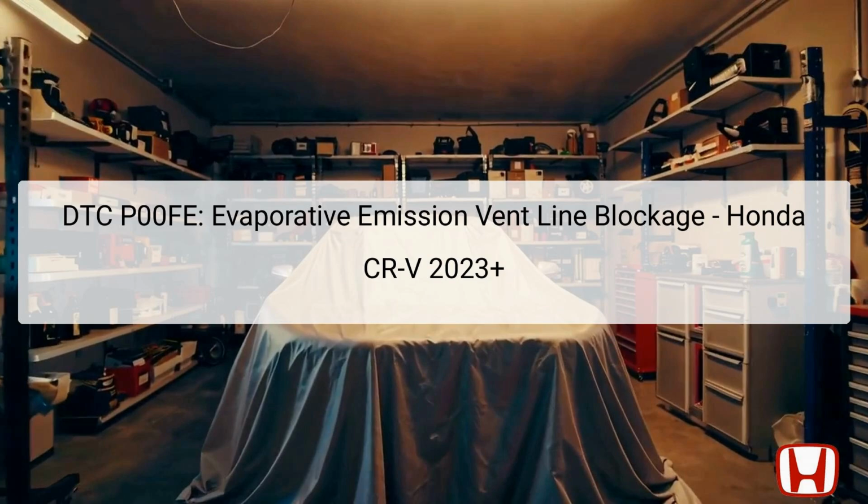The components involved include the EVAP canister, the EVAP purge valve, the fuel tank system, and the EVAP leak check module. These components play crucial roles in managing fuel vapors from the fuel tank, ensuring they're captured and sent back into the engine for combustion instead of being released into the atmosphere.